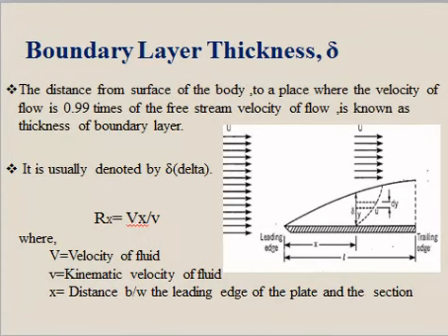We had also discussed the boundary layer region. It is divided into three regions. First is laminar region, second is transition region, where the flow is transiting from laminar to turbulent, and the third region is turbulent region. So the relation for finding this nominal thickness del will again depend on whether the region is a laminar region or turbulent region.